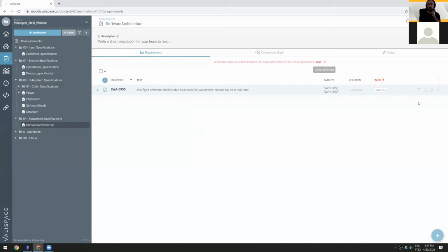Another important point is the saved views. They also save filters. So if you have a filter that you always need to add because of a specific workflow, you can create the filter and then save the view, and you will have that always available.